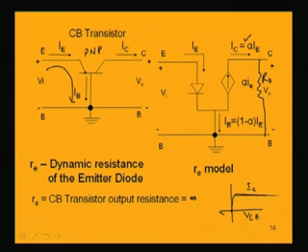So, basically in the active region, this is almost horizontal, means the resistance in the output circuit is so high, it is almost like infinity. So, even if you change this collector to emitter voltage, the current is not going to change, and that fact is the reason why we have not shown R0, or it is almost like infinity. This R0 value is infinity. So, it is well equivalent to not showing, because if there is a part having infinite resistance, obviously there will not be any current flowing in that resistance. So, it is like open circuit. That is why very conveniently we can remove this R0, but exactly the whole circuit will be having this R0 also.